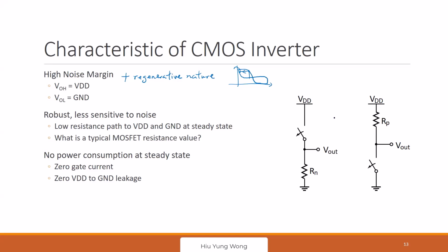You can do some intellectual guess also. Think about what voltage you apply to the drain and what current it gives you. I'm thinking that the VDsat is typically 200 millivolt if we want to be amplifying.